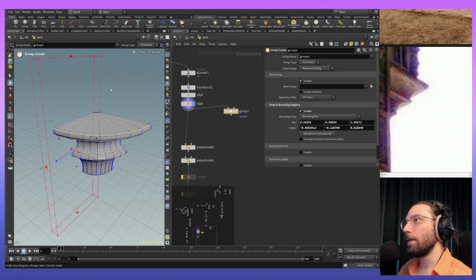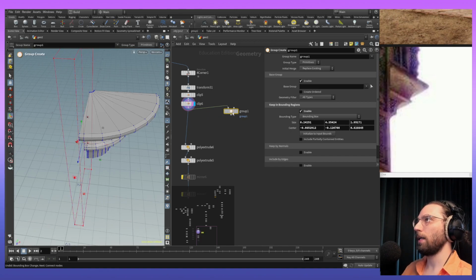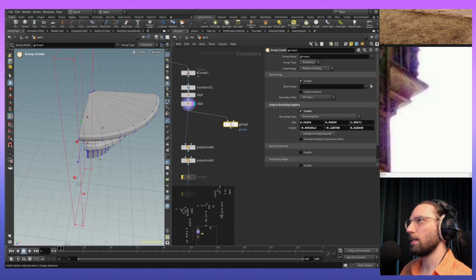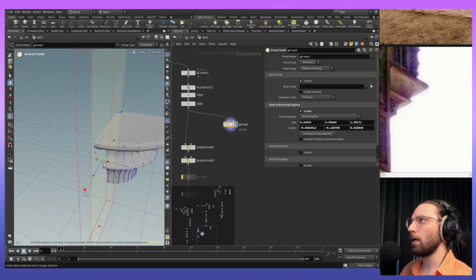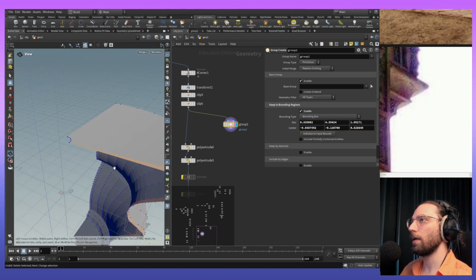All right, guys. If you're not getting a view of what is happening in that bounding box, first of all, we had a mistake here, and that is we didn't connect it yet. So first of all, you need to connect it and then go back inside of here. Make sure you're selecting edges, for example, and then you have to also make sure that you enable the view. Now, as you modify the bounding box, you could see that you are actually selecting faces, or it's just showing you how deep the box is going, the bounding box.